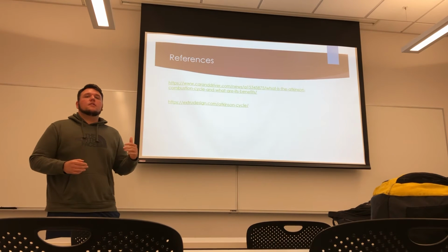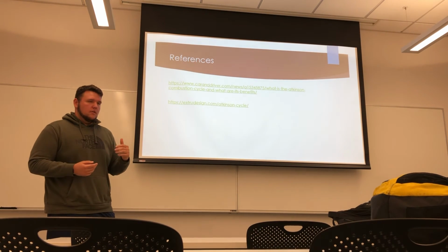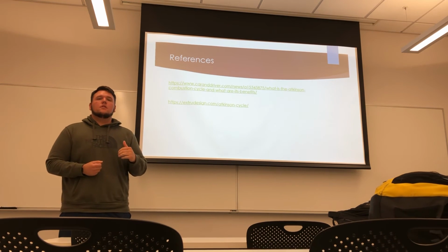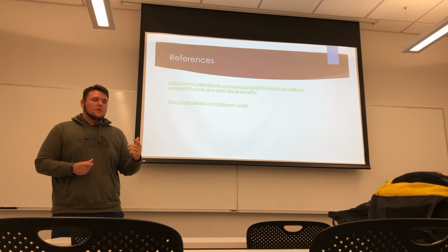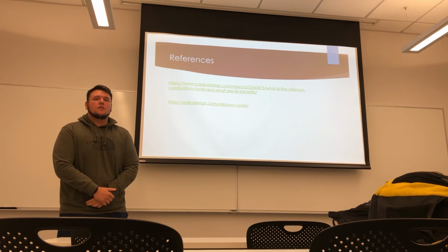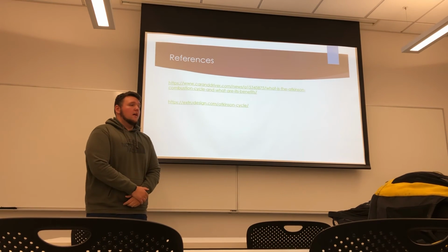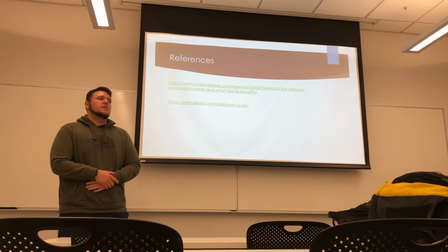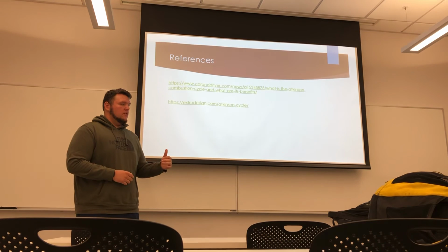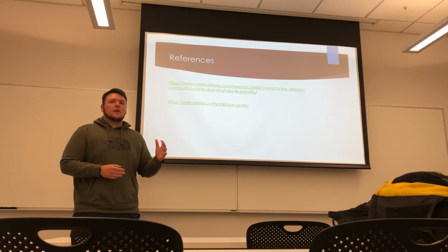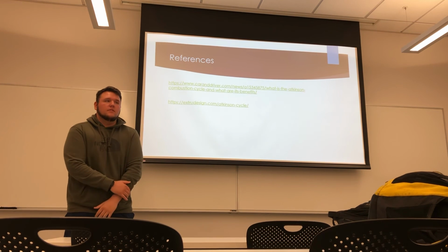So in conclusion, although the Atkinson cycle does give you lower torque and lower power than the Otto cycle, it does give you higher efficiency, which is why these are used with the hybrid vehicles. Another interesting thing is if you add a supercharger to the Atkinson cycle, that's what makes the Miller cycle.